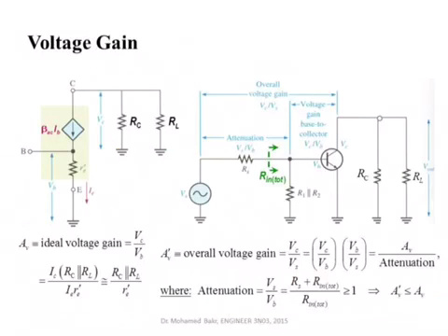Now we move to how to calculate the gain. Calculating the gain follows exactly the same steps, but we'll do it in two steps. First, we'll try to find the gain defined as the ratio between the collector voltage, which is the output voltage, and the base voltage, not the source voltage. So this one here shouldn't be that difficult. You have a current source, beta AC multiplied by IB, here. Then the voltage that you can measure between these two terminals here, plus and minus.